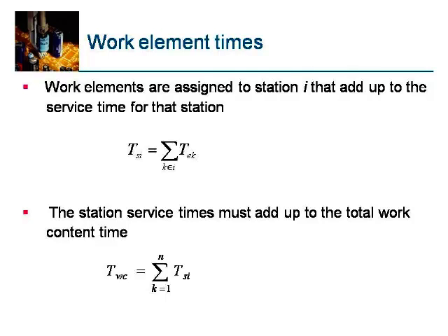The total work content must be given to various stations. The assembly of all operations cannot be performed at only one station, so it is divided among several stations, and at each station certain work elements are performed. While assigning these work elements to each workstation, you need to follow the precedence constraints. At the same time, the total work at each workstation should be more or less equal.